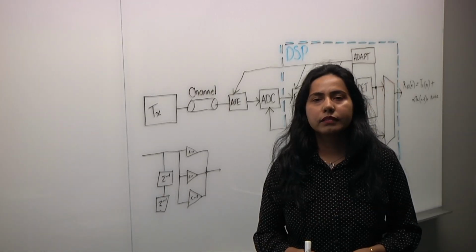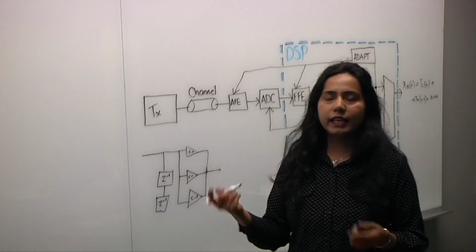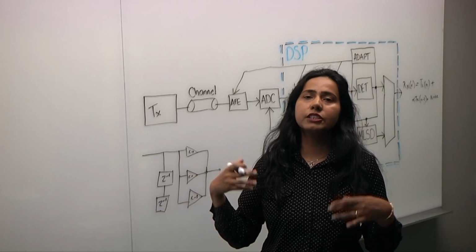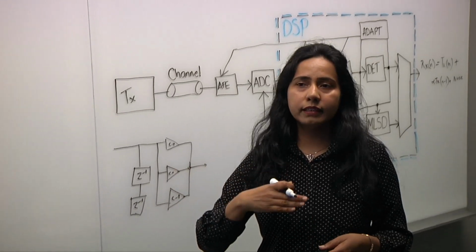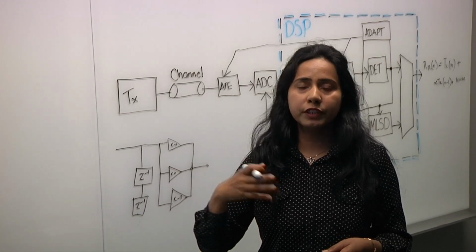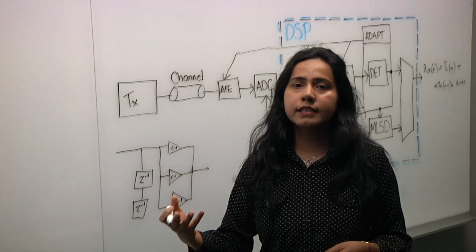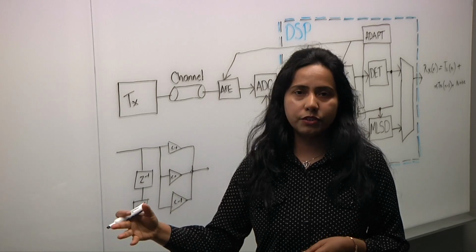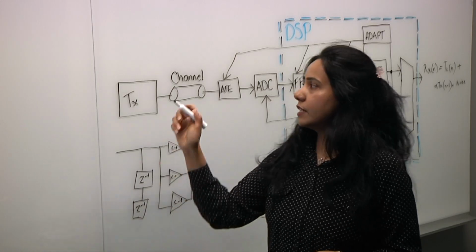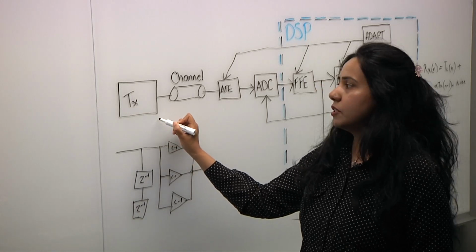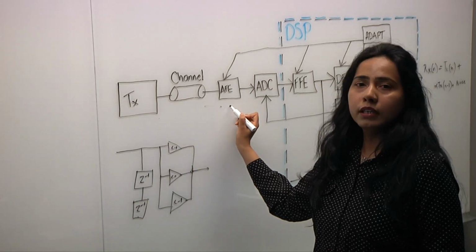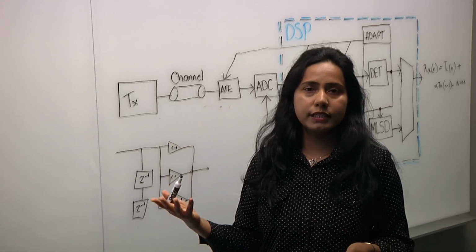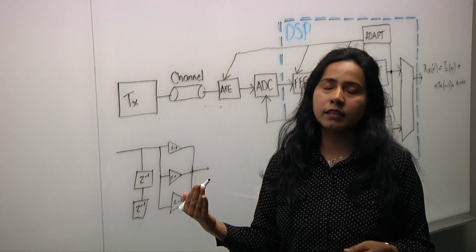Where do DSPs fit into this? Right. So as we spoke, with PAM4, we have more signal integrity challenges because the channel is high speed, and you have channel impairments: the frequency dependent loss is getting higher, as well as ISI, inter-symbol interference, from the channel when your data is traversing from the transmitter of one link through the channel to the receiver side of the link. And so DSP is part of the equalization that has to be built into the SerDes.